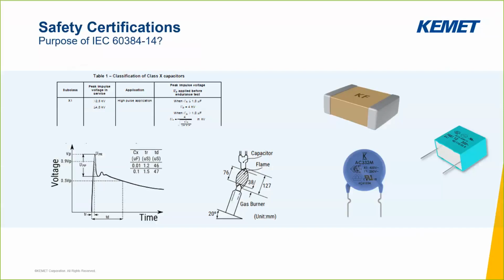Now, IEC 60384-14 provides strict requirements for classifying, qualifying, testing, and marking of the safety capacitors. The classification, such as X1, X2, is defined within the standard, and the capacitor suppliers must meet the specific requirements to classify to those ratings. In addition, the qualification and test procedures are defined within the document to ensure all certified capacitors meet the strict requirements of the standard. These include electrical and mechanical tests, solderability and impulse voltages, endurance testing, active and passive flammability, just to name a few.